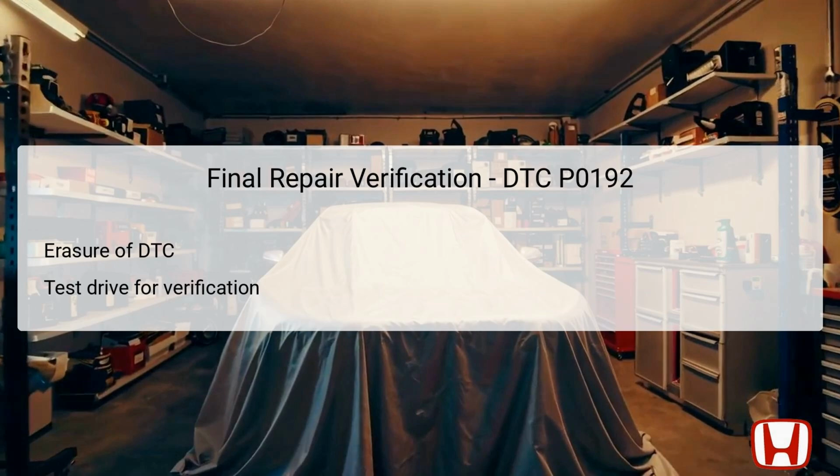Carefully monitor the vehicle's performance during the drive, paying special attention to the engine's responsiveness and any warning lights. If all diagnostics pass successfully without the return of DTC P0192, it indicates that the repair was effective. Continuous monitoring of the fuel delivery system post-repair is recommended to ensure long-term reliability.